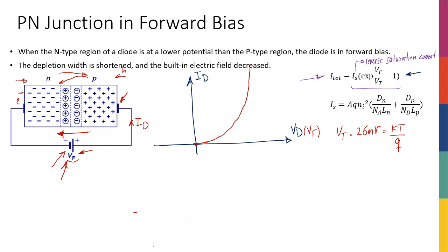It means that it's a reverse bias. It's not a forward bias, right? So VF here being negative, it's like if I have a negative 2 volts here, it's as if I have 2 volts with this polarity, right? We know this from electrical circuits.